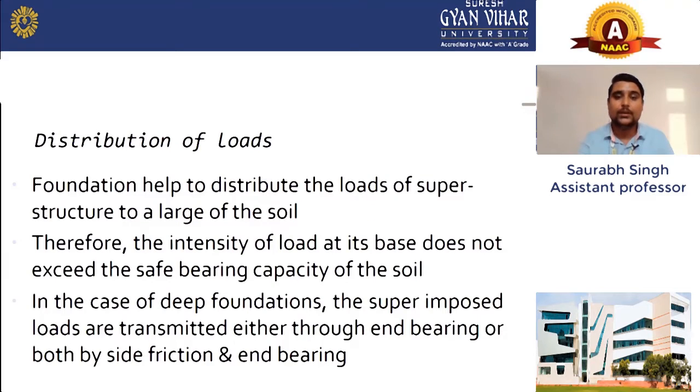These are the functions of foundation, and this is a very important point. Now we will see them one by one. First one is distribution of load. As you can see here, foundation helps to distribute the load of the superstructure to a large amount of soil. As I told you earlier, the superstructure is the upper part of your building.